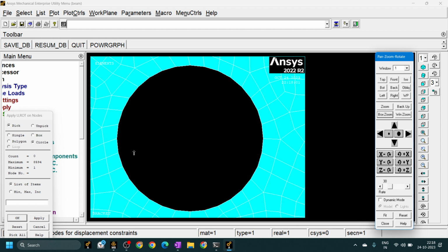So here we can see they have given the zoom view of that part which I have underlined, which I have made inside the rectangle. So after zooming, we will make the nodes. We will make the different nodes on the base, on the periphery of the circle. So here I will take on the center, left click, and I will go like this. Wait, from here go to center and touch the circle. Like this. So here we have created the nodes.